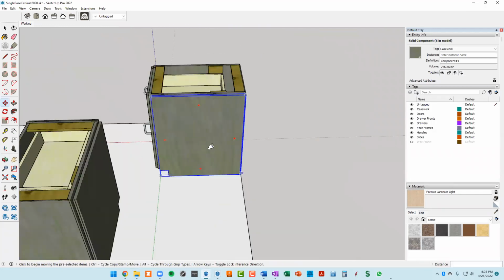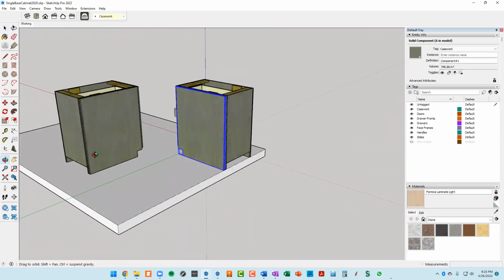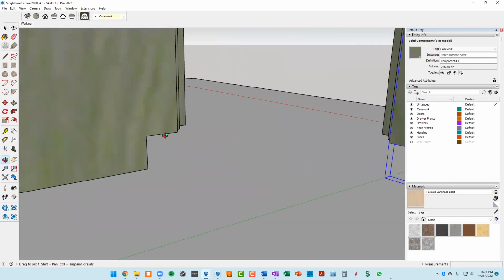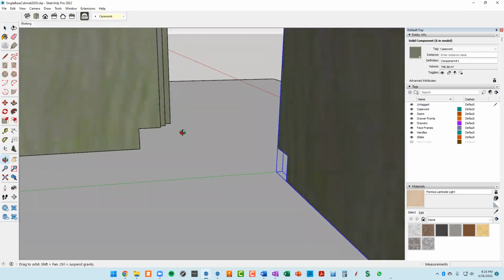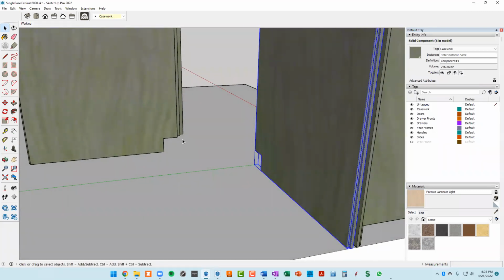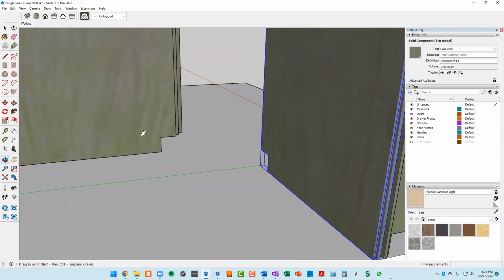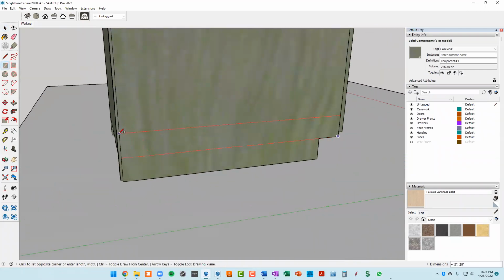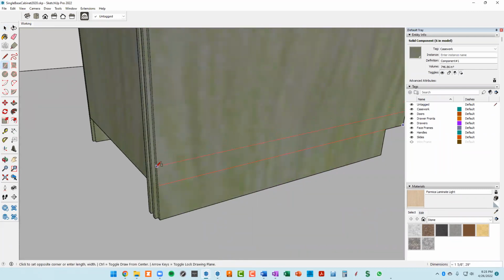Okay. So I think the next thing I would do is to do the bottom shelf here. So the bottoms of our bottom shelves were aligned to this notch for our kick plate. So I think that's where I would start. I'm going to get a rectangle here, start there, and go across to this side. And you can see I'm going right up to that rabbet, which is good. So we're not going to have to resize that later on.